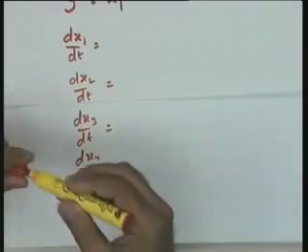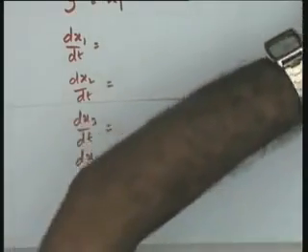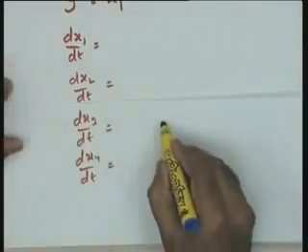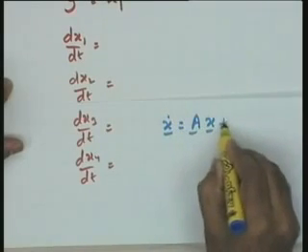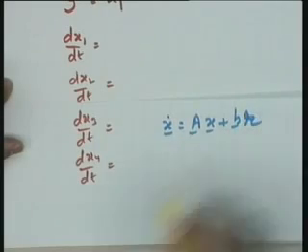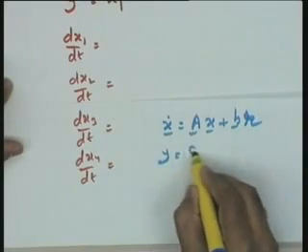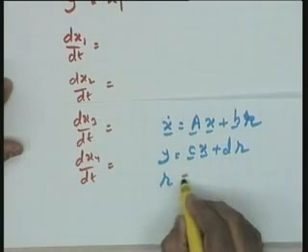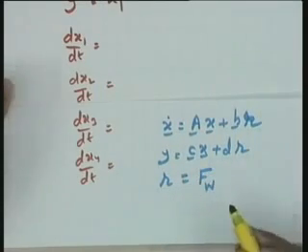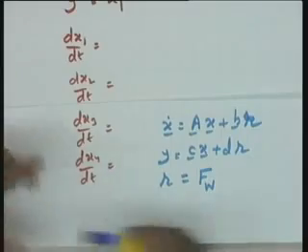And then these four equations can suitably be put in the standard format of x dot equal to Ax plus Br, y equal to Cx plus Dr, where r, as you note, is nothing but your fw, the input to the system, which is the disturbance input.